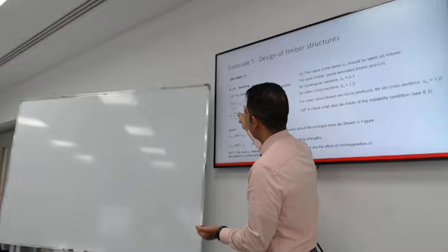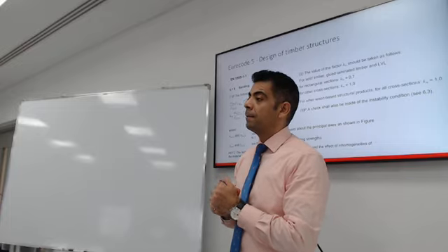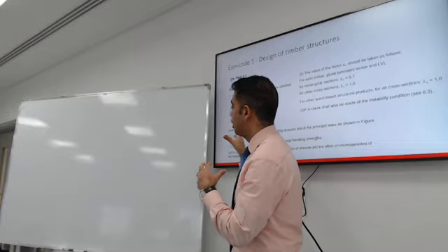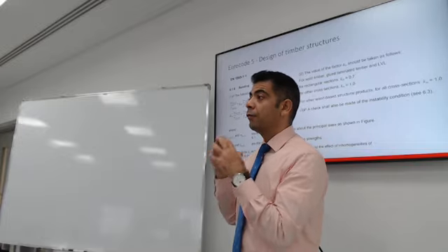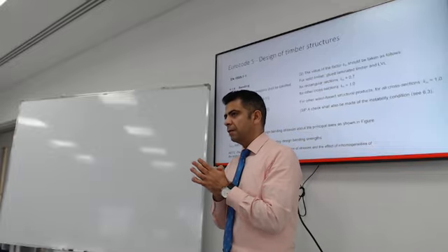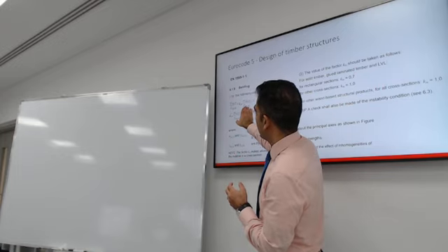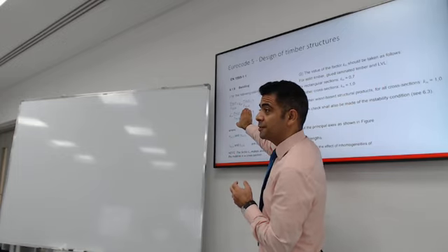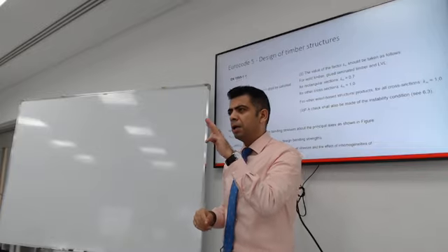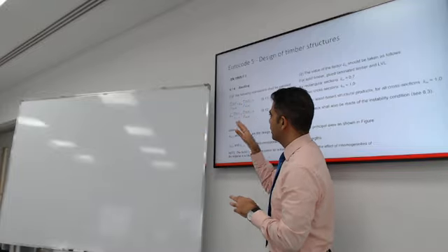The bottom factor, fm, is the design strength of wood. I would say this is equivalent to f yield with the proper reduction factors. So there are a few reduction factors that go into calculating this term. This term only has 3 modification factors that go into calculating it.